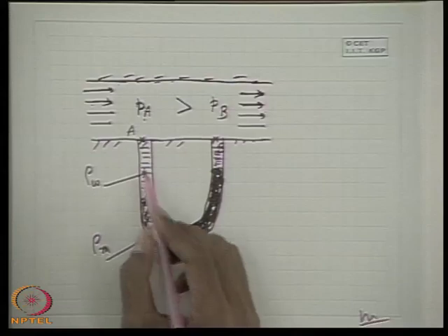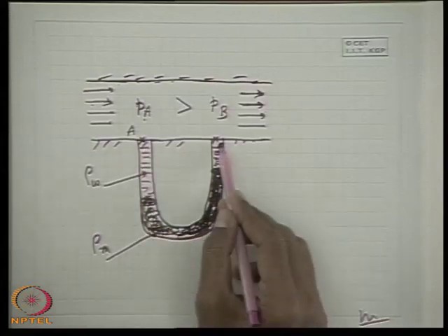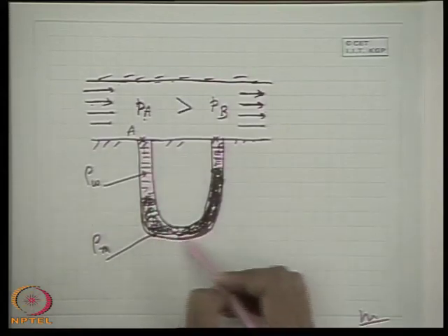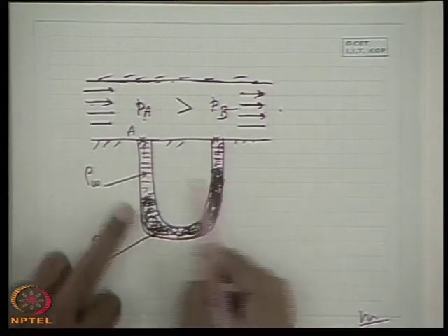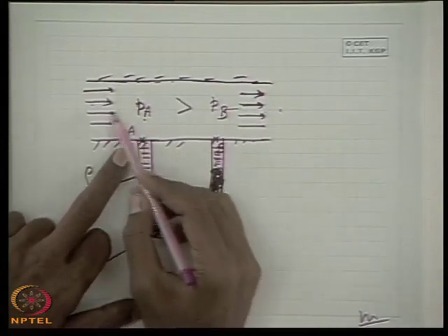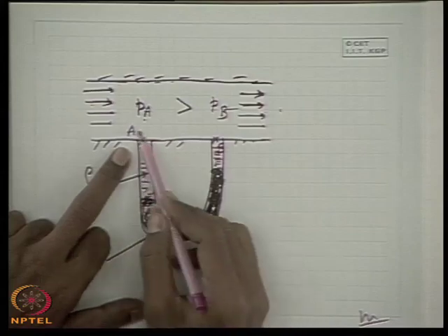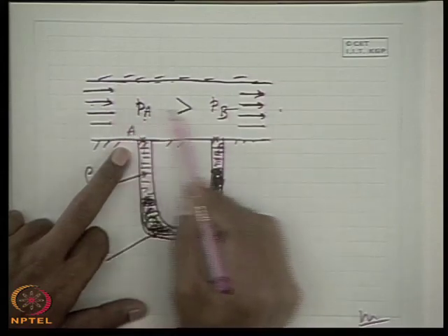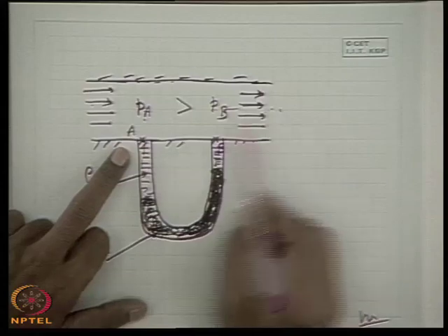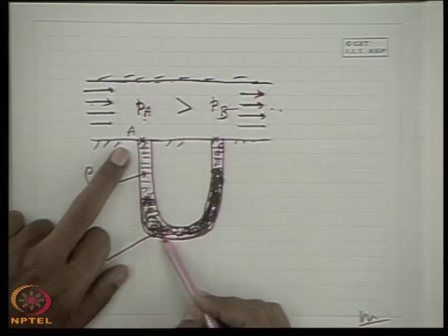That means, because on both sides this will be in contact with the liquid and this is of higher density. Then what we do is create a bypass line, a secondary line where the fluid is at rest, while the working fluid flows like this. If we do not have this high density fluid, and simply connect it with a U-tube, the working fluid comes through the U-tube at higher pressure and goes like that. That means we will be creating a bypass channel like that, where the main flow is taking place like that and a part of the flow goes through this bypass line.